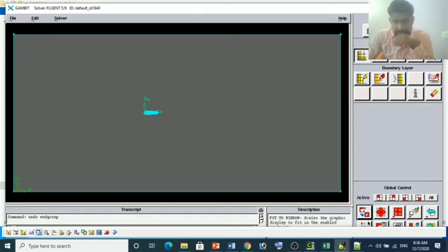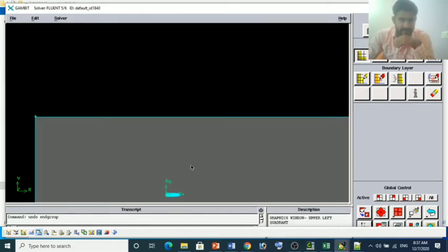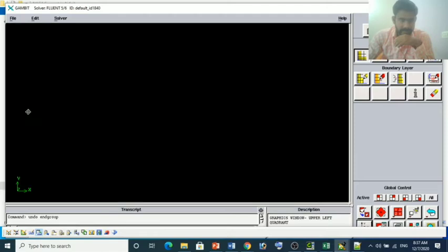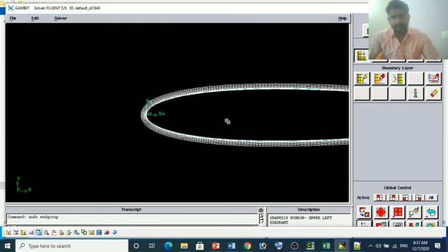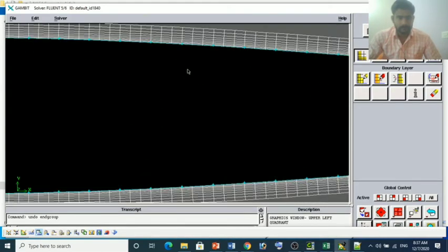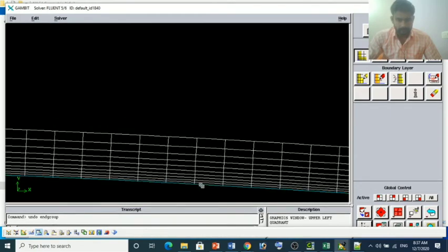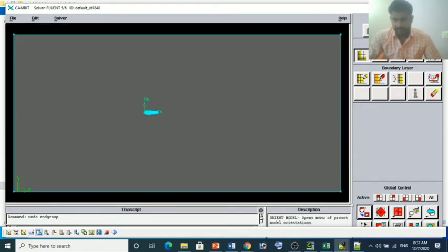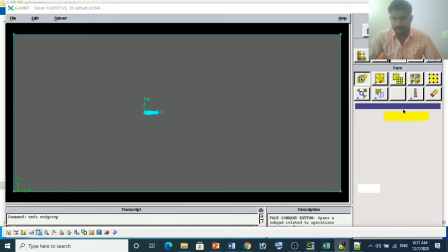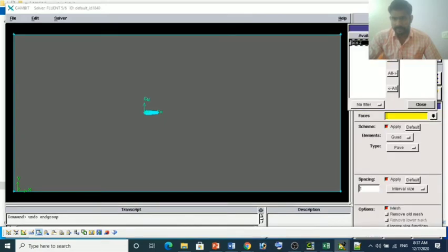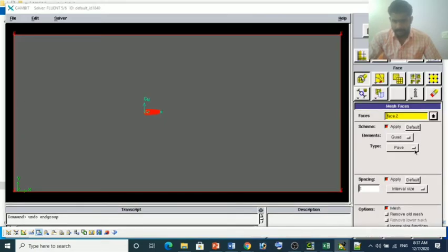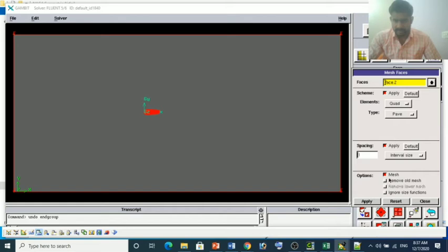meshing is there. This is the boundary layer meshing creating steps. So what I did is, I selected the first, then for the remaining we will select a face mesh and we will do the triangle mesh over there. It will come automatically. We'll select the only one face, right, and quad paving. We'll see whether it's working or not, otherwise we'll move to another one.